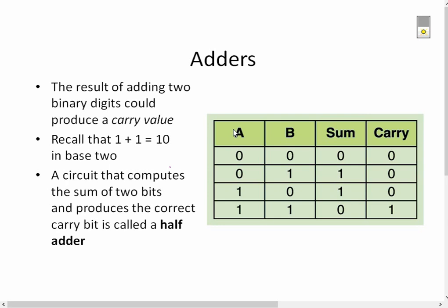So an adder circuit, particularly when we're looking at adding binary numbers, has the following truth table or characteristics. So 0 and 0 means I have an output, or sum if you want to call it that, of 0, and I might have a carry value. 0 and 1 means I have a sum of 1 with a carry value of 0. 1 and 0, meaning that I'm adding 1 to 0, means I have an output of 1 and a carry value of 0. And 1 plus 1 is 0 with a carry value going to the next position over of 1.